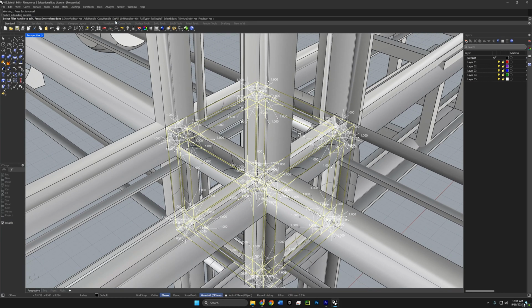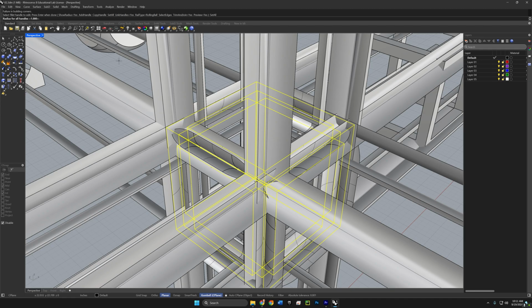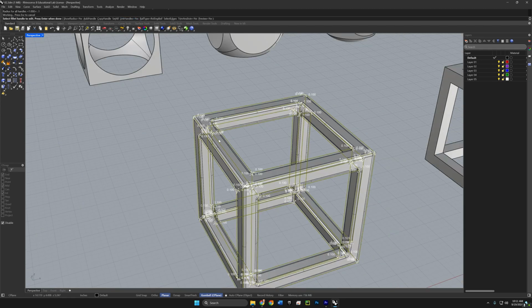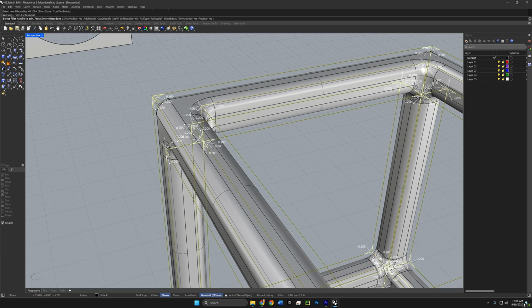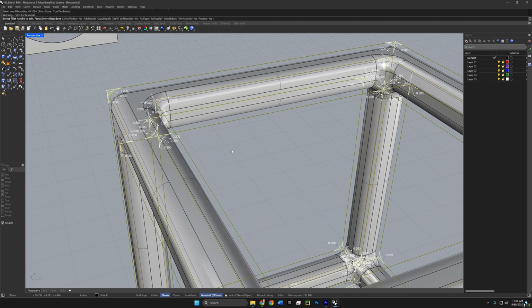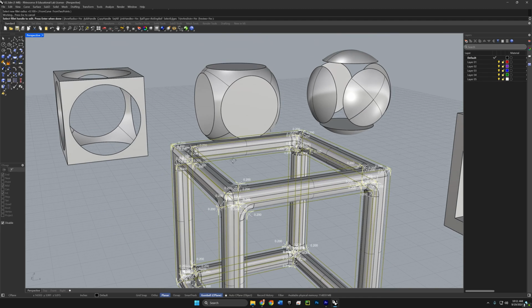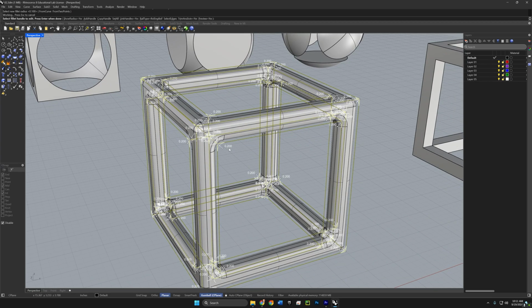So let's click on Set All. And we can set this to 0.1 in this case. With link handles set to yes, if we don't like this result, we can come in and actually drag this around, drag any of the handles to affect all of the other handles. If link handles were turned off, you could independently adjust each of these different radiuses. So once you're happy with the result, you can push enter.